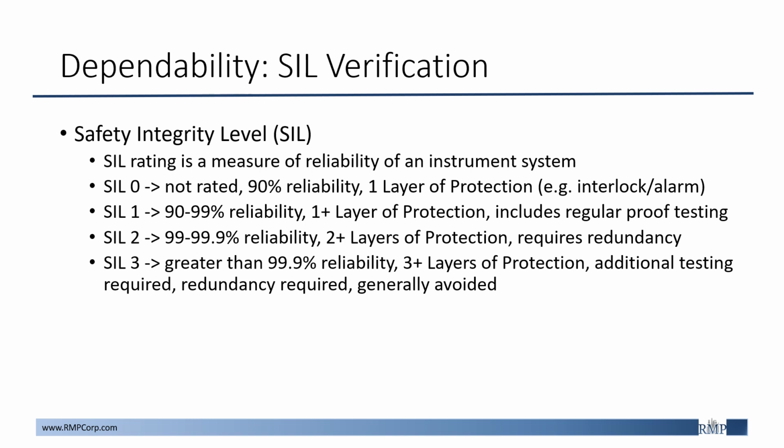This is because of its heavy testing and record-keeping requirements needed to maintain this rating. It requires at least 3 layers of protection and has the highest risk reduction factor. So that's why the maintenance, testing, and inspection practices that go into our IPLs are heavily correlated to the presented SIL ratings that we've shown here. And that's why this should help capture the importance of how your dependence heavily affects your IPL and its credit when considered during your LOPA.